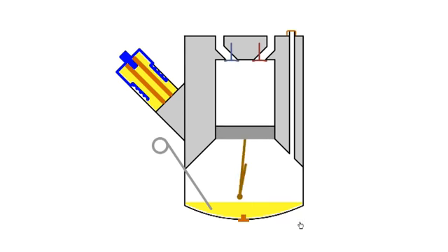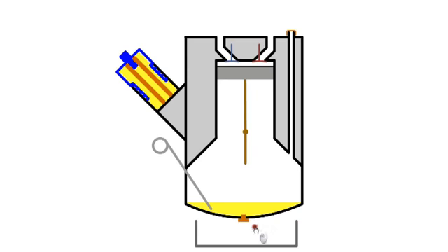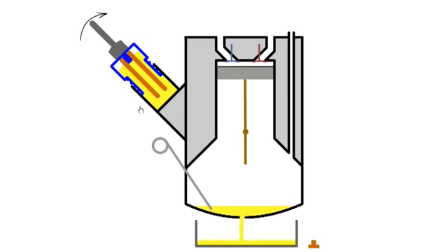Before changing oil, we run the engine for a short period to warm the oil. A container is placed under the sump, the filler cap is removed, and we open the drain plug. While the oil is draining, the oil filter is replaced. This is a cartridge filter which is contained in a removable housing. It's sometimes called an eco-filter, as only the element is changed, saving on material and disposal costs.